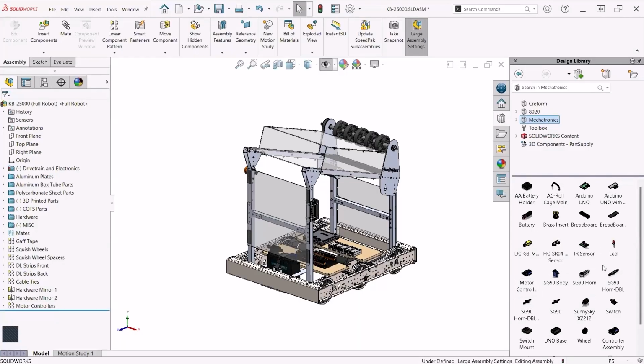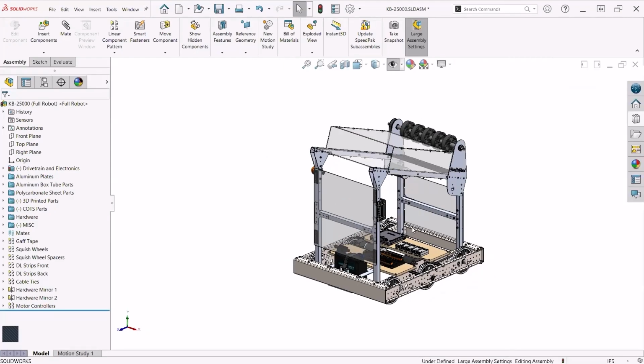So now I have a library of those, and I keep those in my design library so that I can use those in multiple different kinds of projects. All these are a link to a folder on your hard drive, and that's all that they are. And you simply click this button up here, add file location, and browse to that folder, and you can have access to those, and you just simply drag and drop those things right in there.